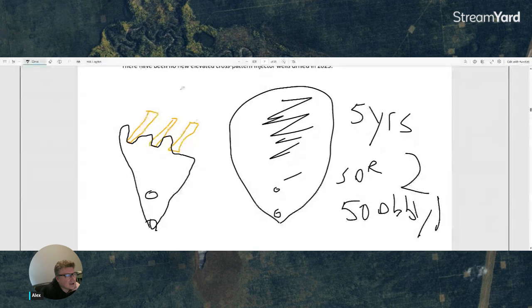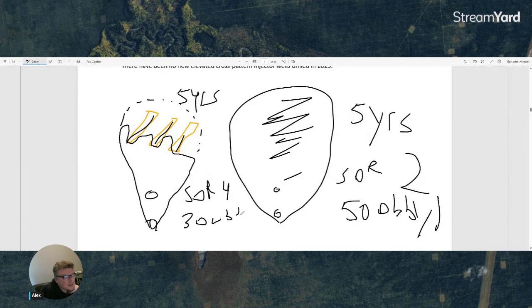Something like that. So then after 5 years, this chamber will have SOR of 4, steam to oil ratio of 4, because now you're trying to inject that steam to the bottom hole pressure, but the response of oil production is not as much because those non-permeable regions hinder chamber development, where ideally you would want it to be here. You would want that, but it's just not happening because of those complex geologies. And oil production rate could be, let's say, 300 barrels a day, like here.